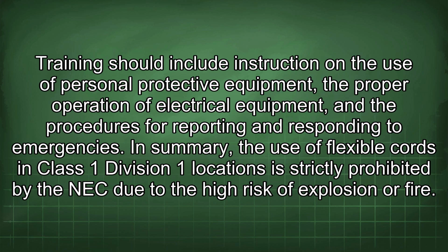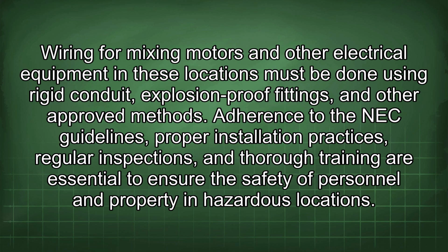In summary, the use of flexible cords in Class 1 Division 1 locations is strictly prohibited by the NEC due to the high risk of explosion or fire. Wiring for mixing motors and other electrical equipment in these locations must be done using rigid conduit, explosion-proof fittings, and other approved methods. Adherence to the NEC guidelines, proper installation practices, regular inspections, and thorough training are essential to ensure the safety of personnel and property in hazardous locations.